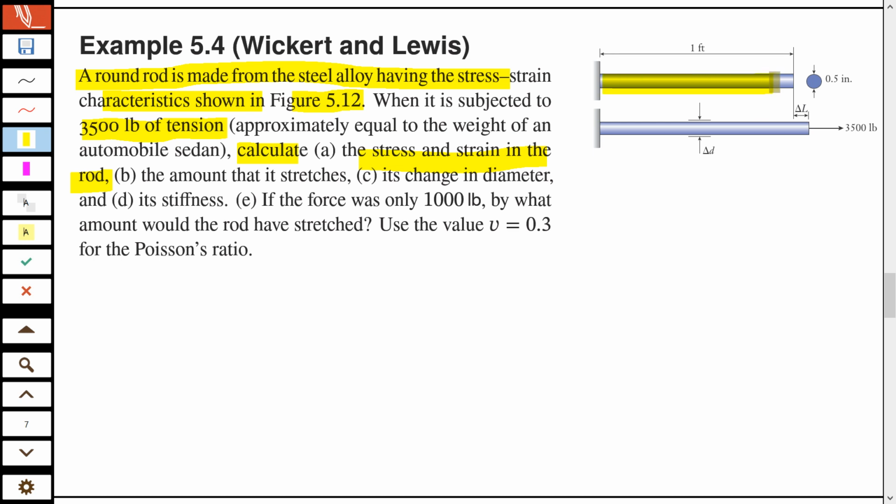Stress क्या होगा? So tension over area. तो आपके पास यहाँ पे टेंसाइल लोड है T और यहाँ पे एरिया हो गया, and you know how to calculate area from this diameter, ठीक है? So you know area, you know tension, you just calculate this. So that is something which you will find out. Now the next thing is strain, yeah? Strain आप कैसे calculate करेंगे?